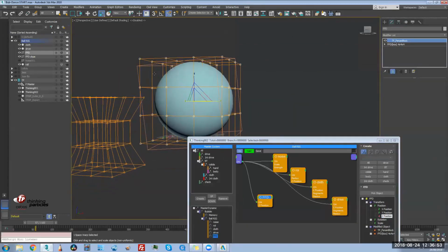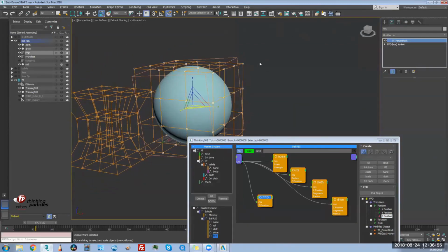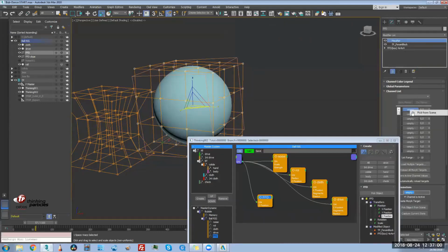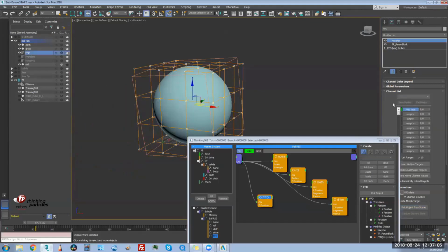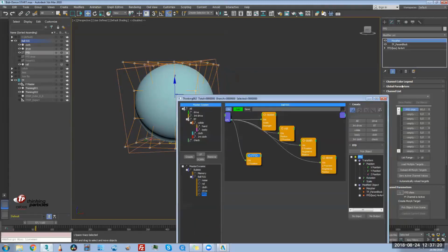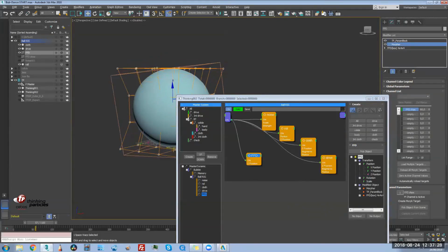Basically, we want to have a gradual change of the deforming grid. So the best way to do it is to use a morph modifier. So basically, we assign the deformation gradually, and we can also animate it if we want. So this opens the door to several tricks. And this is a very efficient and fast way to control the deformation of the FFD space warp. So this is the reason why I use a morph modifier.